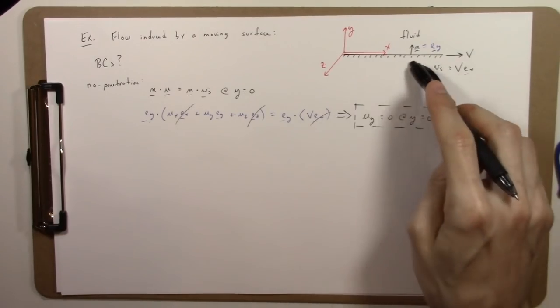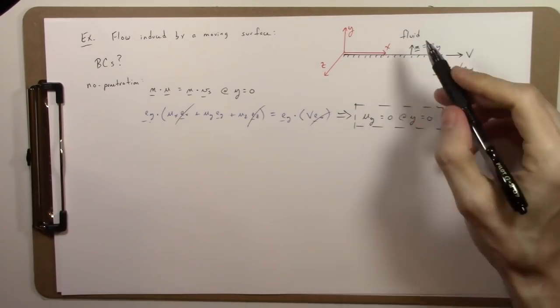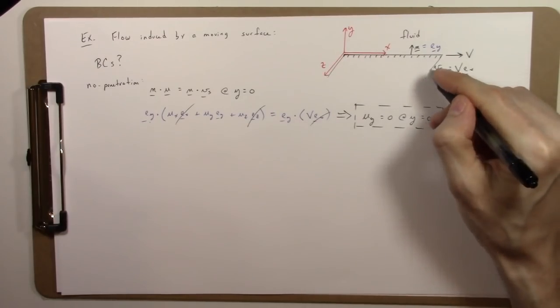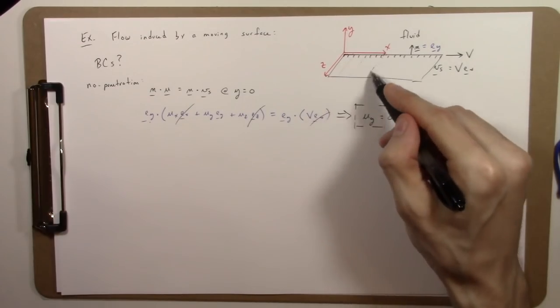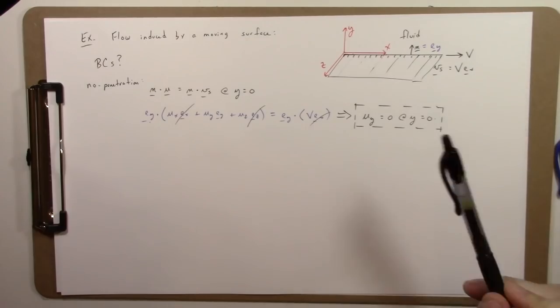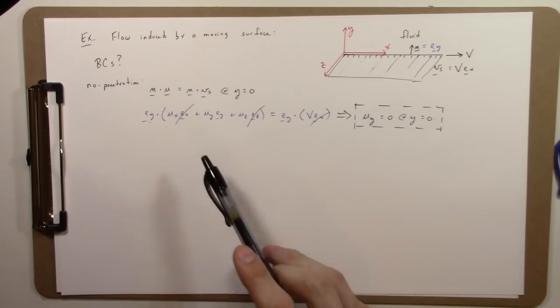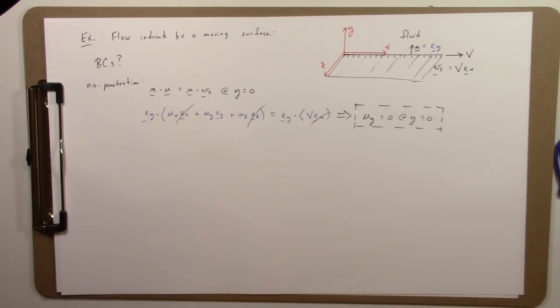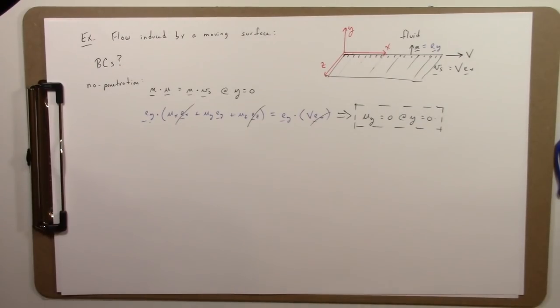In this case, it's the x-axis, so the normal vector here is y, pointing into the fluid. We're assuming that this plate extends out in the z direction, like this, and therefore the fluid lies above it. And so the normal direction n is Ey. We say that Uy is equal to 0. Now, if you can do this by inspection, you don't have to write out every step I showed here. This is just to show you the general procedure for a more complicated case. But in this case, it's pretty obvious, and so you can just state by inspection what the result is if you so desire. Now we can look at no slip.